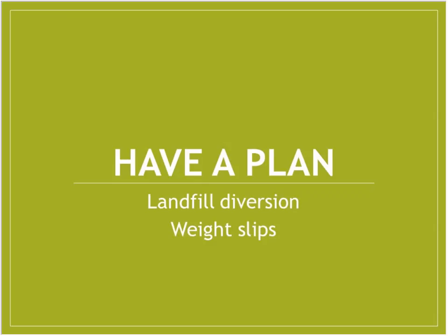Having that plan is very important, making sure everybody on the job site understands where each item needs to go, and having it posted, so that it can be diverted from the landfill. Whether that's recycled, composted, or whether the asphalt shingles on the existing home are going to be used as roadbed, you name it. Obviously, every local area has its own different challenges and opportunities, so make sure to investigate those and then put a plan together. And again, if you can do single-source recycling, where the waste hauler recycles it for you, that might make life a lot easier.